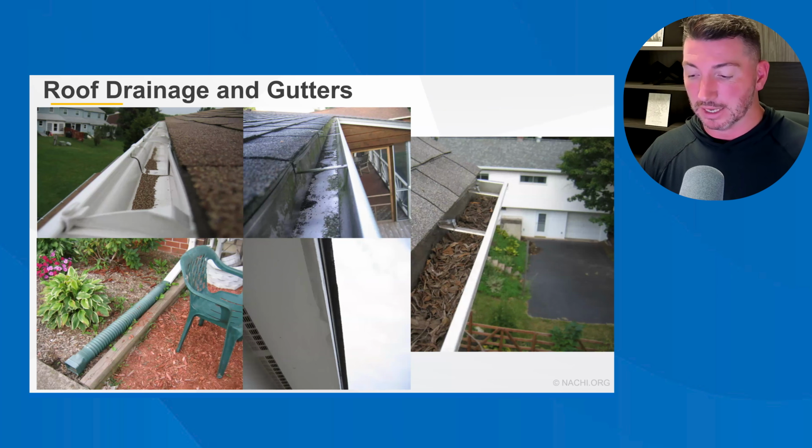It's a best practice. The best practice I always heard was a quarter inch of drop for every 10 feet. It's a best practice that may be used by a home inspector when observing a gutter system. The point is that the gutter should be sloped towards the downspout. And a very low sloped angle may not allow a great amount of water to move effectively, and a much greater slope causes the water to move at too great a speed, potentially resulting in overflow at caps and corners.